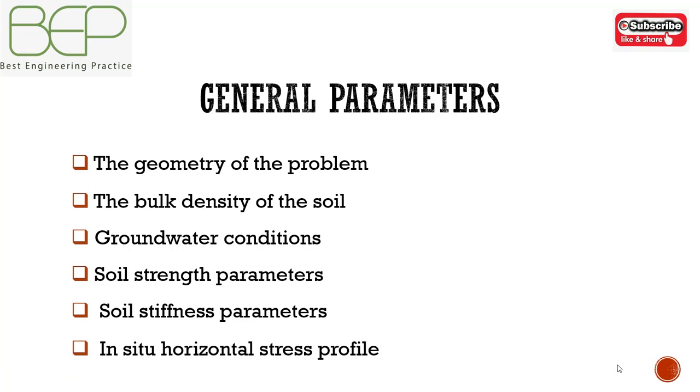In situ horizontal stress profile. When computer analysis involves constitutive soil models based upon both elasticity and plasticity, it will be necessary to have a detailed knowledge of soil stiffness, effective strength parameters, and the initial in situ horizontal stress. In situ horizontal stress is both difficult and expensive to measure, and can usually only be derived from either self-boring pressuremeter tests in situ or from suction tests on laboratory specimens.